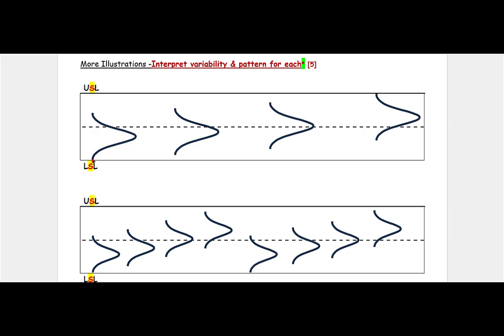So what's happening here? Well, it looks like our average is shifting, which means our process average is shifting upward over time. If I look at variability, it's pretty consistent across the day. So are we making defective product? Not yet, but it certainly looks like we're headed that way in the next round.